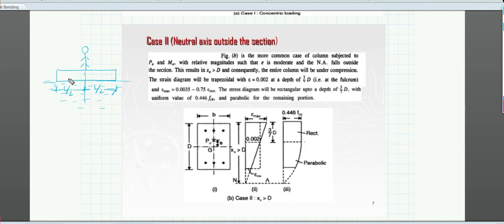Now if you are exactly at the center, what will happen? The stress will be uniform. It will be just the upward stress, whatever upward reaction the water gives to the plank, it is the same, right? And this value will be how much? If your weight is W and suppose I'm talking in terms of a uniaxial case, meaning only a one dimensional case, then if this is the length, the stress will be W by L. I'm talking about only the 1D case.